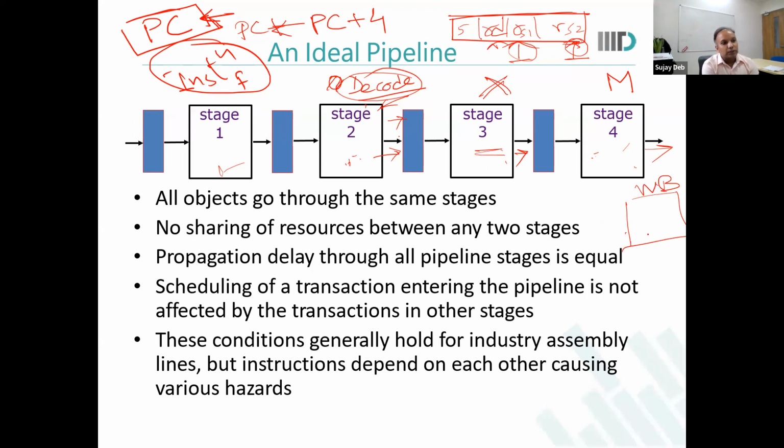Let's say I have an instruction that loads a value from memory to a particular register. I have read the content of memory, and the content is available now. In the write back stage, I will update that content into that register. So basically in the write back stage, we update our register files, the general purpose register files.